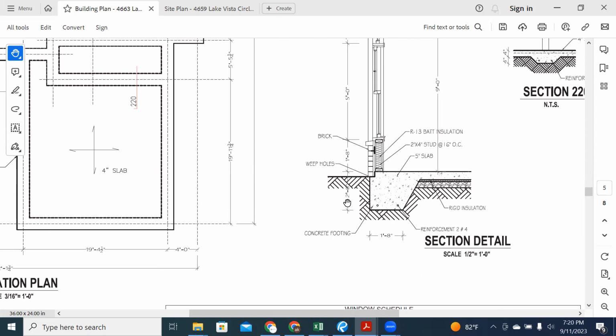In the video, I have my tape measure and I showed where our width was 20 inches. And then to the top of our slab, you would have had 24 inches, maybe a little deeper in some places. Keep this in mind because when it's time to do our calculations for our concrete, we got to do the footings and then the slab. Then we're going to add it all together based on the formula for calculating volume and get our concrete. In the end, we are going to do a little math and see what we come up with, and then I will share with y'all what we actually did.